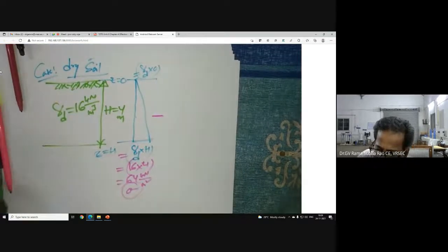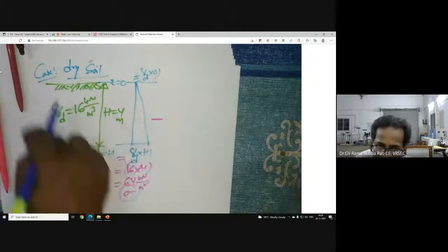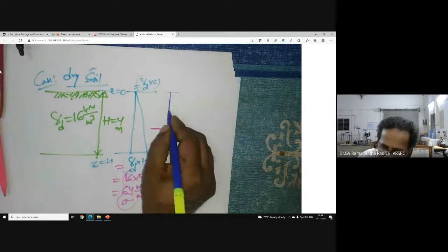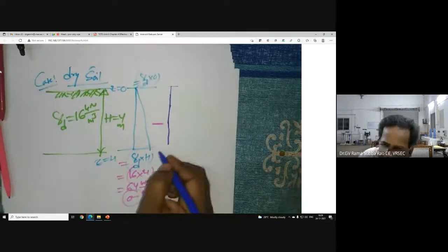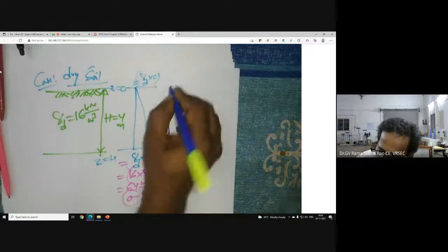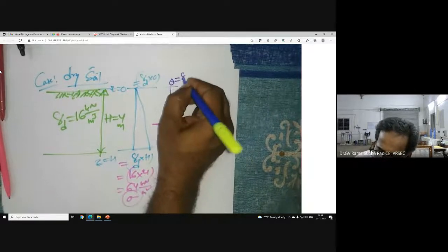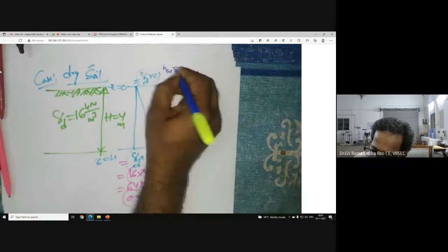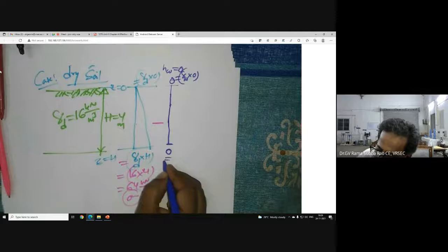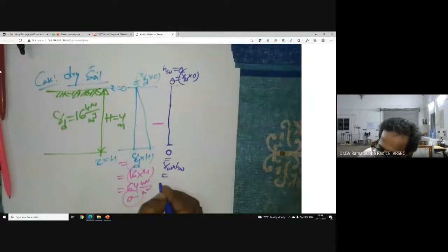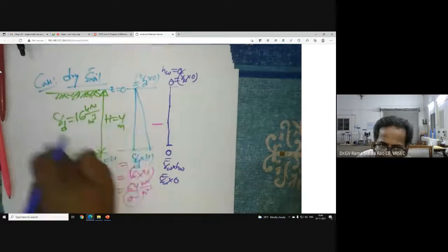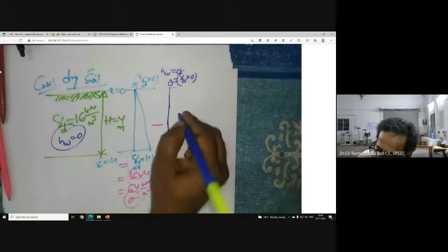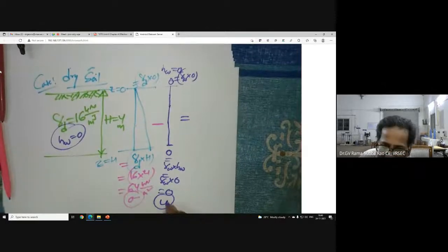Somebody is very much interested to know the pore water pressure. No water table is there. No groundwater table is there. So undoubtedly now we are having more confidence about drawing the pore water pressure distribution diagram. It is 0, 0. Gamma of water into 0, because the head of the water is 0. I'm trying to write here the head of the water is 0. So here also gamma of water into height of water. Gamma of water into 0, because no water table is there. Head of water is 0, literally 0. Now what is the final answer? This is the pore water pressure distribution diagram.